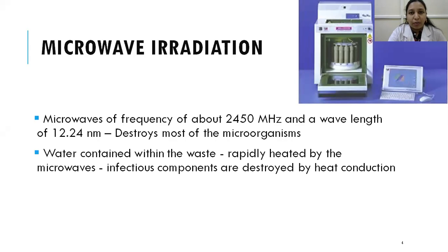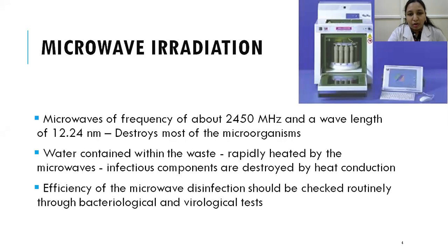So water contained within the waste is completely reduced, and all the waste is rapidly heated by the microwaves. So the infectious components which are present in the waste are completely destroyed by the method of heat conduction here. So microwave disinfection, though this is a very useful method, it must be checked routinely through bacteriological and virological tests to check its efficiency, whether there is complete reduction of the microorganisms or not.